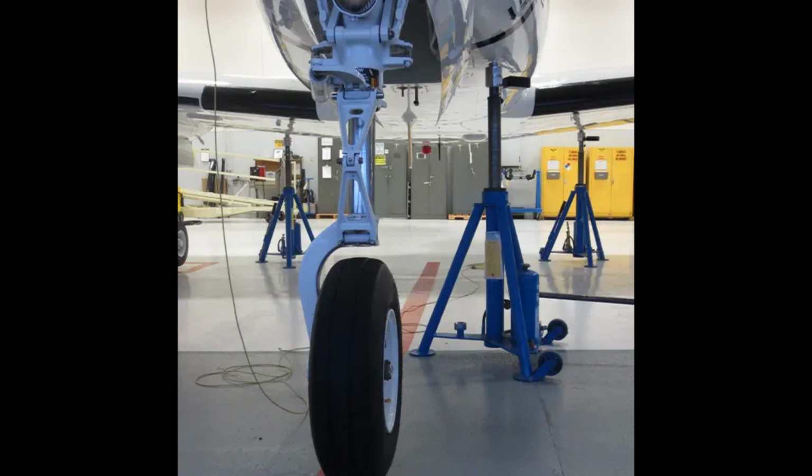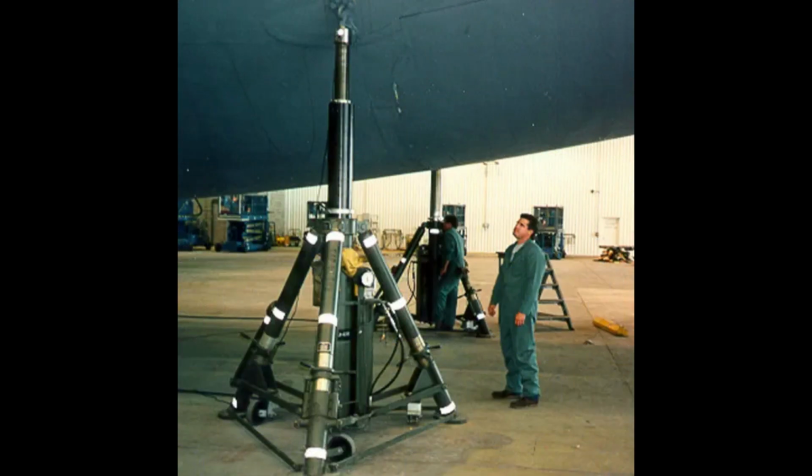If the aircraft has spring steel landing gear and it is jacked at the wheel, the landing gear will slide inward as the weight is taken off of the tire, and care must be taken to prevent the jack from tipping over. For some aircraft, stress panels or plates must be installed before the aircraft is raised with wing jacks to distribute the weight over the jack pad. Be sure to follow the recommendations of the aircraft manufacturer in detail anytime an aircraft is jacked.